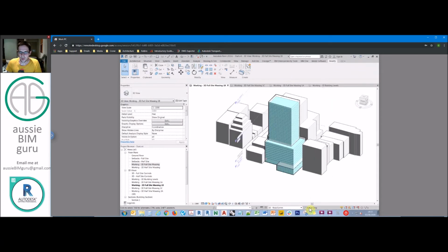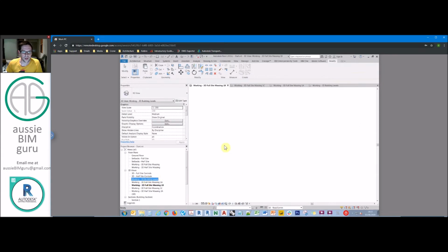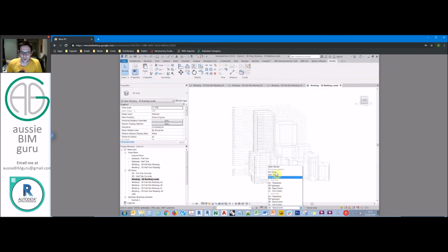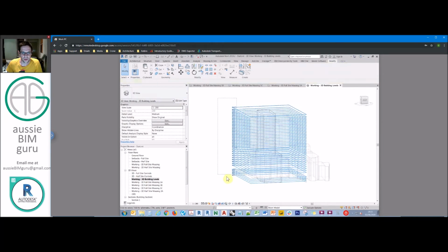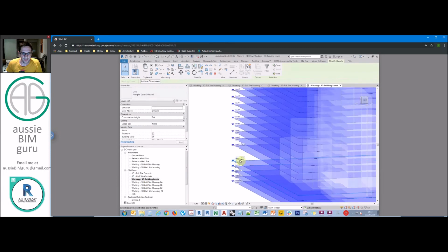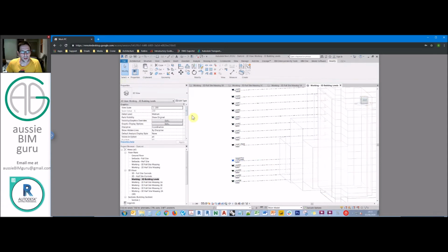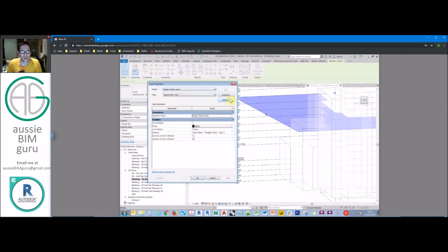Okay. And let's say we wanted to work with a different level mix for our other ones. So currently we have 3.1 meter floor to floor for our residential zone and 4 meter floor to floor for commercial. But another option we want to pursue is a full commercial fit out. So this is a 4 meter floor to floor all the way up to the bar level. So what we need to do is actually establish a second set of levels. But one problem we have is that currently we do have a set of levels for what we call mix 1, which is our standard mix. So what we'll do is we'll just change the name of their level type, and we'll just call that typical level mix 1. And then on top of that, we're also going to create another type called mix 2.